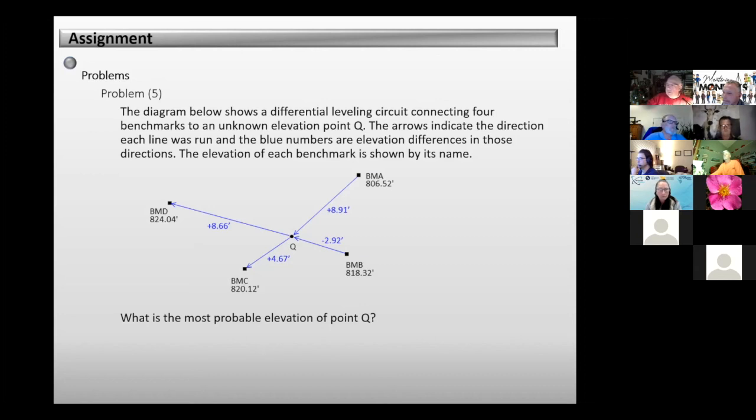Knowing what we know now, we'd write an equation with a residual for each one. We get 4 equations with residuals. We'd square them, take partial derivatives of them, and set them equal to 0. Well, in this case, you don't have to do that, because that one point by itself is connected to 4 elevations. All you've got to do is compute the elevation from each of those 4 points, get 4 elevations, divide by 4, and get the average that way.